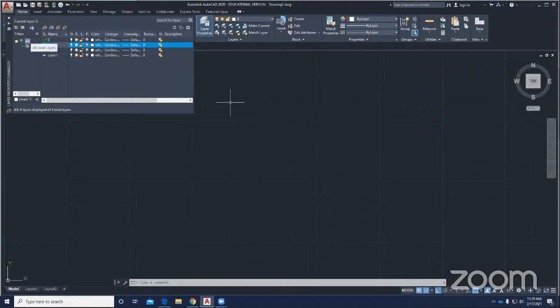There are ways that you can label these. A lot of times they'll say something like arc plan or something of that nature. So it really does depend on where you are, but you want to set up your layers prior to beginning your drawing is the general idea.